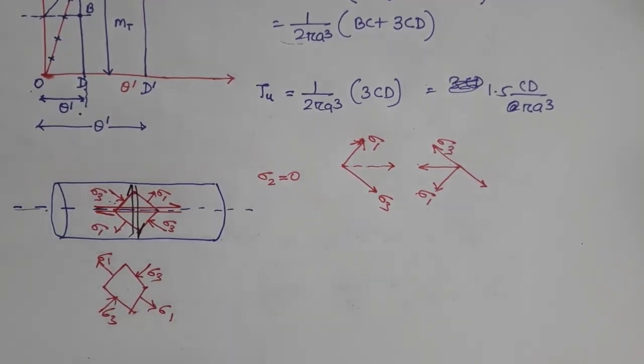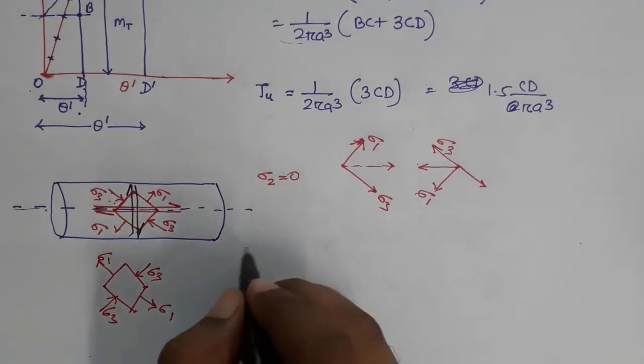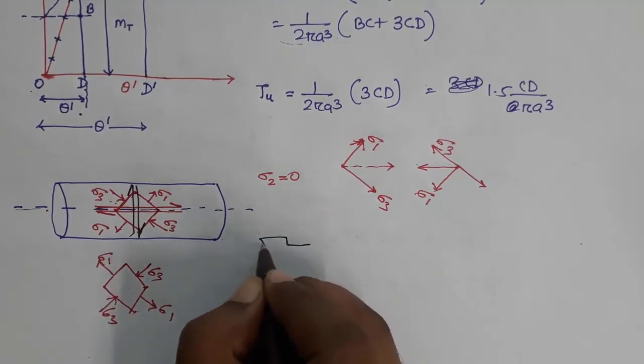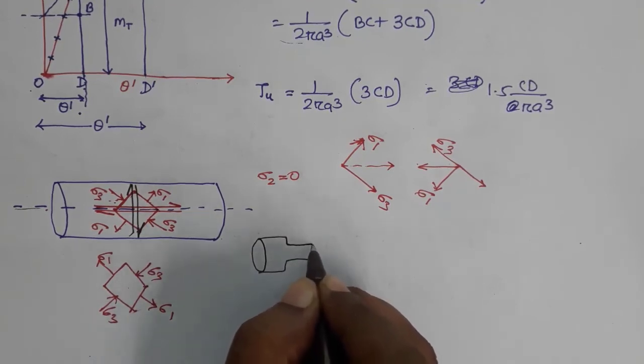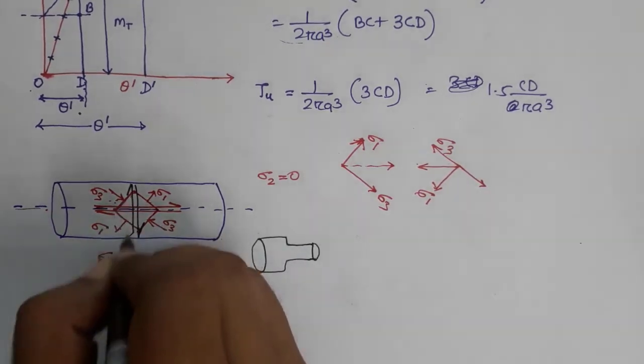So this will be the scenario, and as you know, shear stress causes the plastic deformation. So dislocations usually move because of the shear stress and not because of the tensile stress. So if you have a ductile material which you are testing in torsion, then the sample looks very similar to a tensile sample. So you have a grip and then this will break almost perpendicular because the shearing is happening like that.